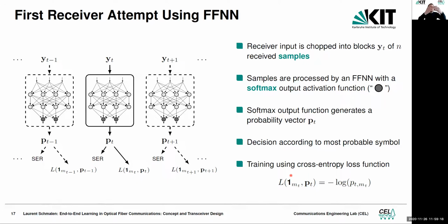Obviously, whenever we have chromatic dispersion, which smears the signal, the chromatic dispersion from the neighboring blocks is not treated. So this is essentially being treated as inter-block interference. So we may see that there is some limitation. Let's look at some simulation results.